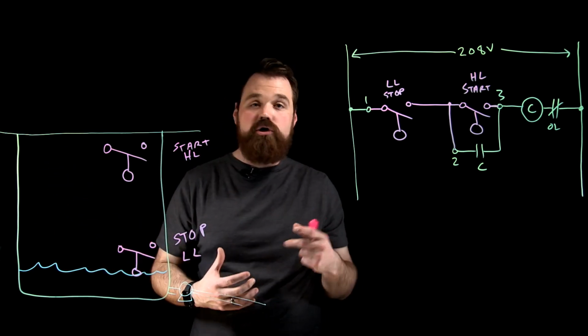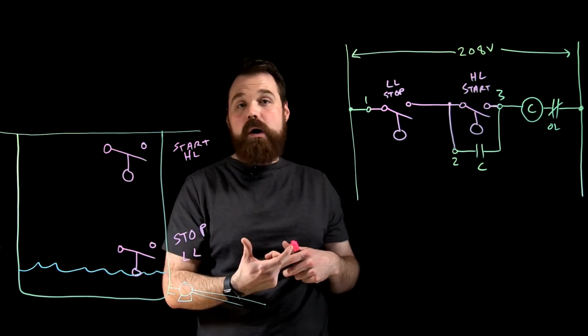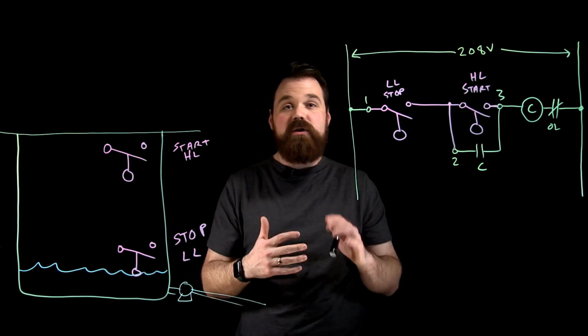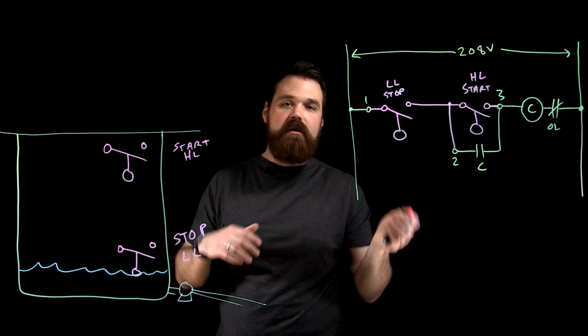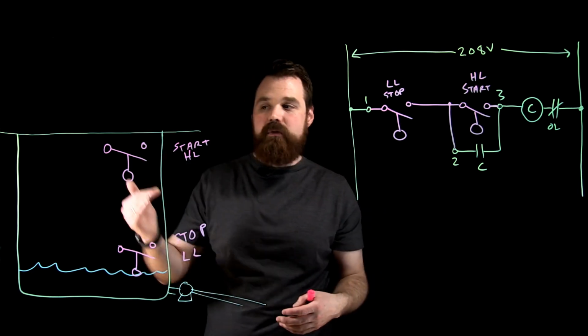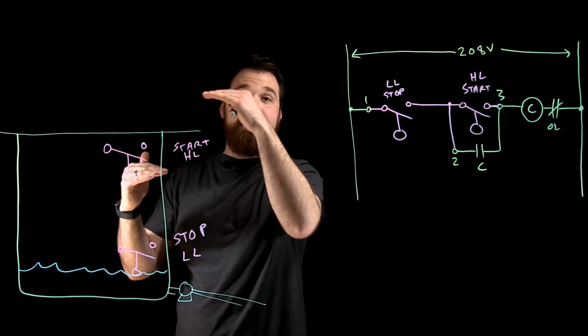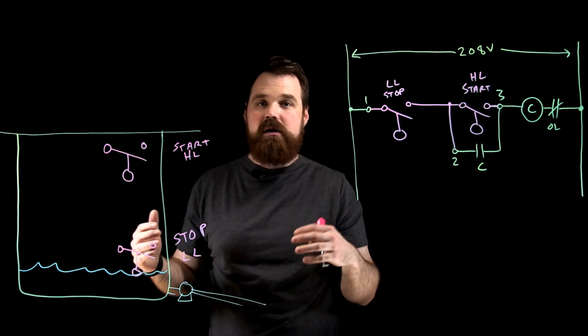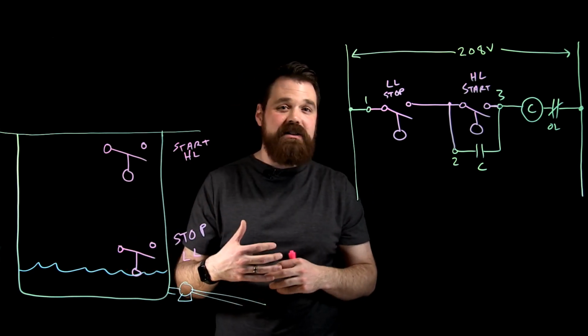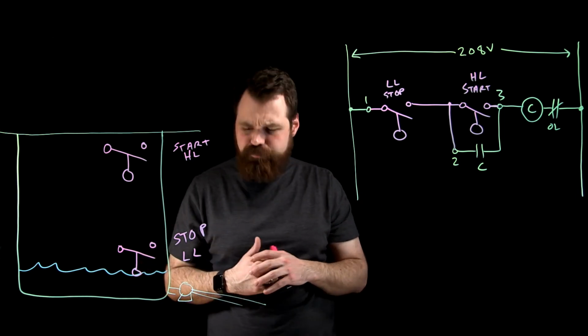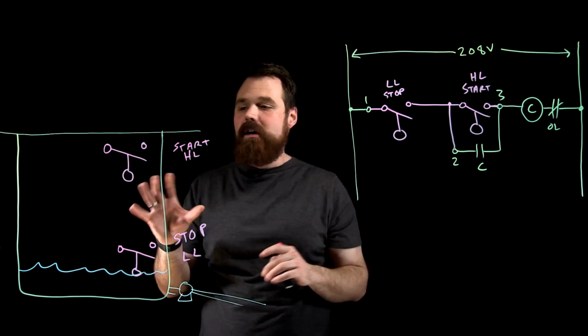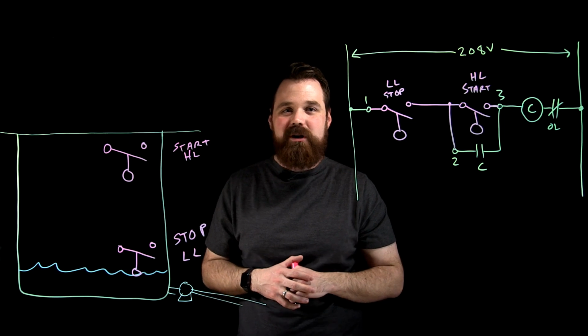There also might be a controller in place, very often using something like a smart relay or an alternating relay, which will switch between the pumps so only one of them is running, then the next one runs, then the next one runs. If we reach a high level or a second high level, both pumps can run, or we can even hook it up into an automated system to send out an email to any maintenance workers or anything like that. This is just kind of the basics of how you would want that control system to work.